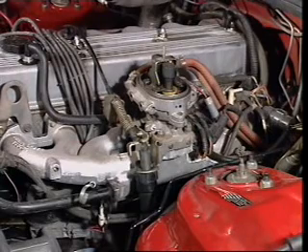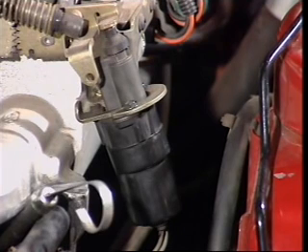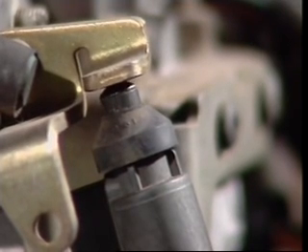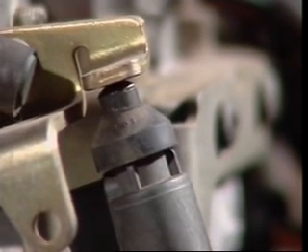When the idle speed is controlled by the position of the throttle plate, a DC motor may be used as a variable throttle stop. The controlling circuit can let current flow through the motor in either direction to extend or retract the linear actuator.